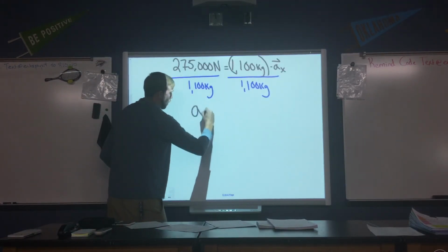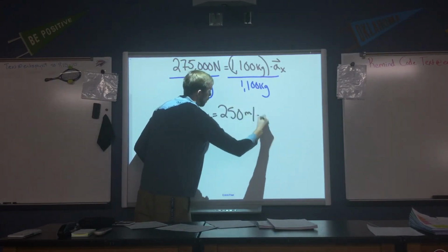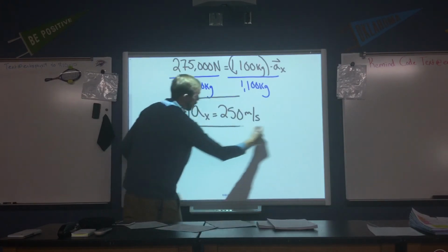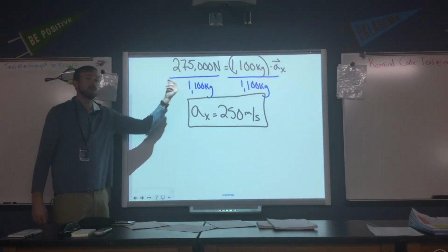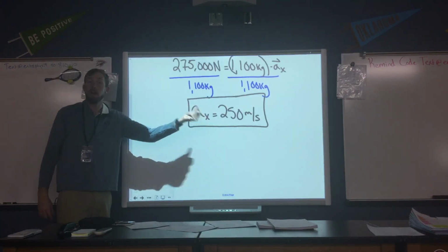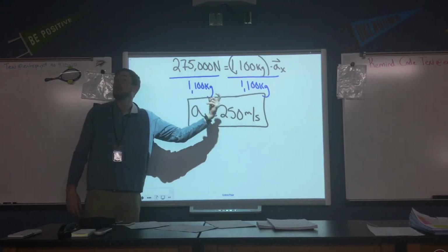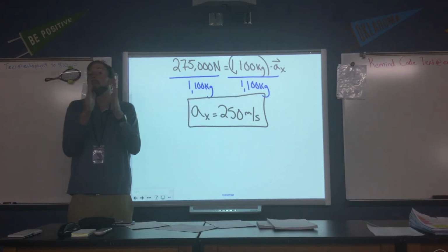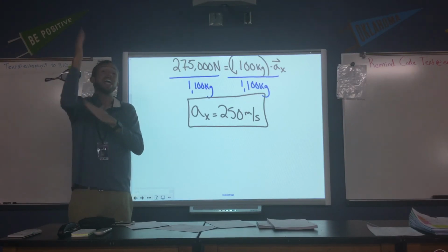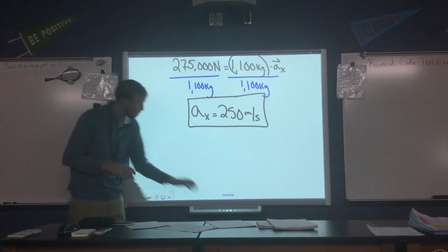Now, that's going to seem like an extremely high acceleration. Remember, this is describing a car that's going from roughly about 45 to 50 miles an hour down to 0 miles an hour in a very, very short span of time. So even though that acceleration value might seem really high, it's because our car is undergoing a very, very abrupt stop, a very high change in velocity in a very short time.